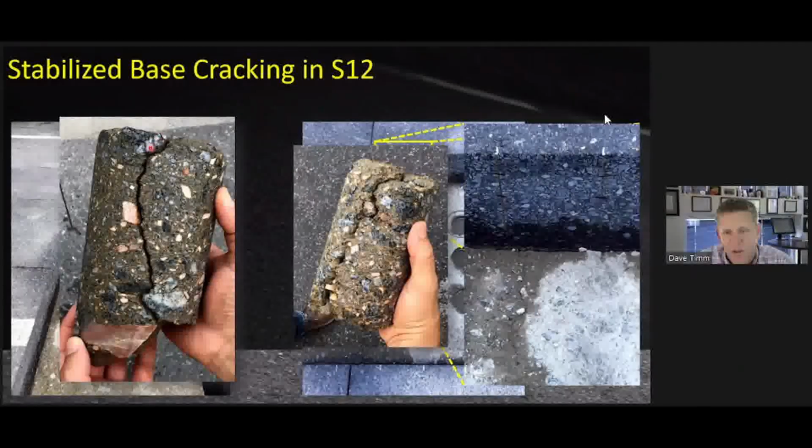It was cracked all the way through. So they were full depth cracks through that cement stabilized layer, and yet somehow they did not propagate up through that CCPR. We're still studying this. The CCPR is a different kind of a thing. I've heard Dr. Diefendorfer talk about it as, you know, that the foamed asphalt that's in with the wrap is sort of like spot welding particles together. It's a good way to think about it, but it has a different kind of cracking resistance. I think had we put more of a normal AC on top of this, or something that wasn't spot welded, we might have seen cracking propagate through this.